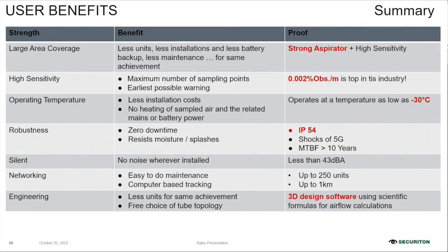I will summarize my presentation: we are using an LED detector. MTBF is more than 10 years. A 2-channel model is available with area coverage of 560 square meter. It can do double knock, suitable for extinguishing facilities. Other models have coverage of 720 square meter to 5,760 square meter, and you can use them as a redundant system as well.